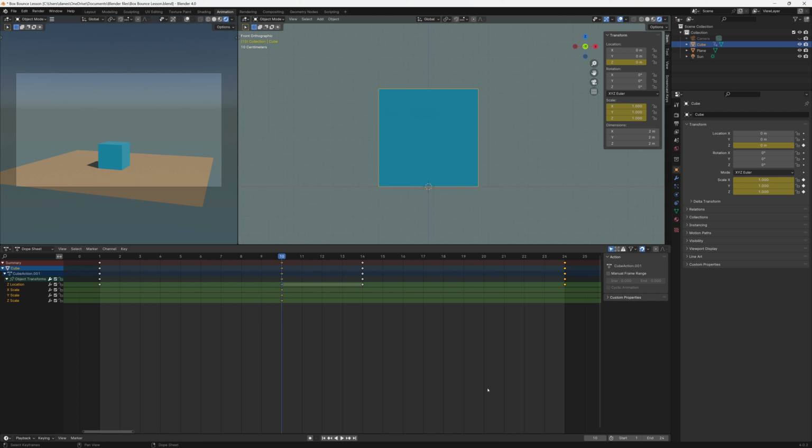Now we're looking at eliminating all this counter animation that would normally be your safe place when you animate. We've got to start learning how to be more efficient. So on 10, no scaling yet. Then we go to 12. This is when it's going to scale. How much scaling? Let's go on Z. It's going to squash it. Let's say 0.5. That's a really exaggerated one.